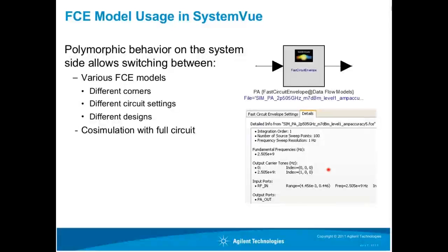As I mentioned earlier, I do have the option of co-simulating, so I can actually run the real circuit within SystemVue by co-simulating onto the Linux environment. Now, that sounds great until you actually try to do it. In the example that I'm going to show later, the SystemVue sim for LTE runs in 3 seconds or something like that.